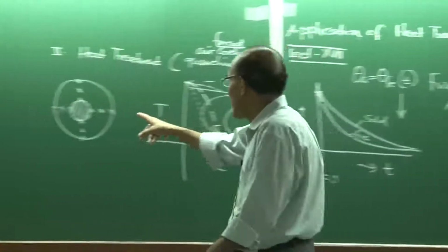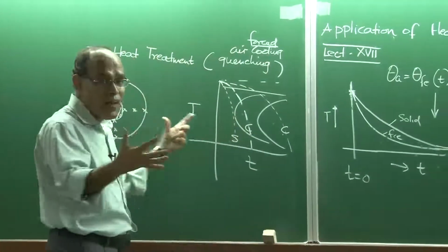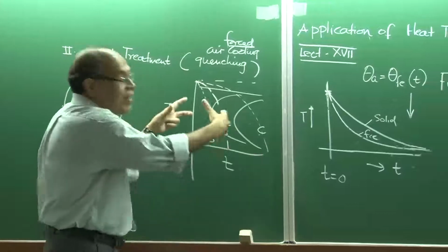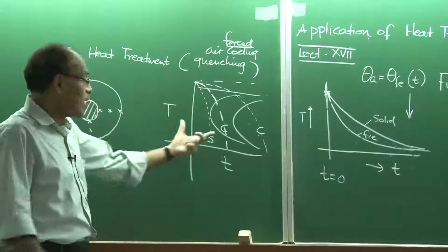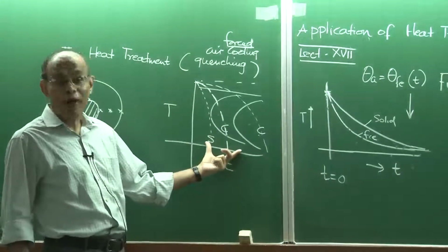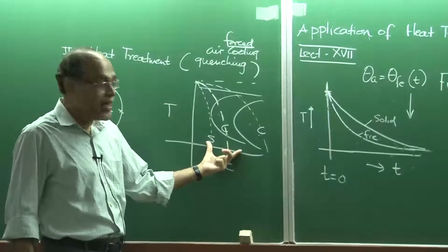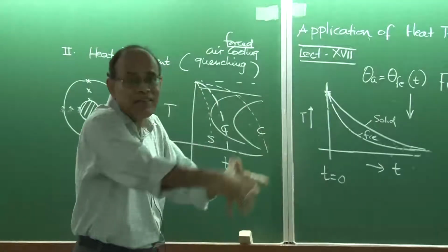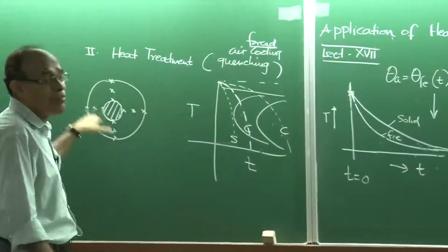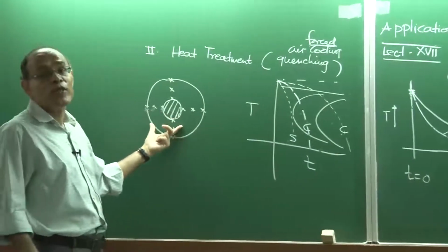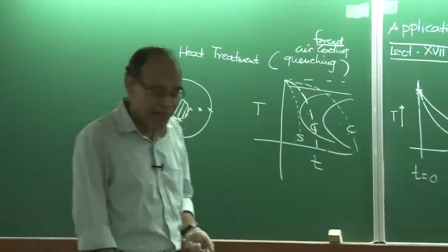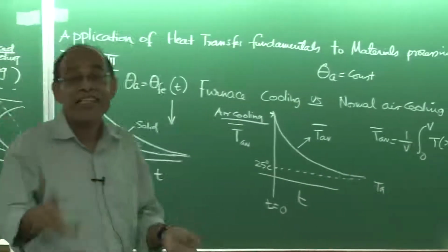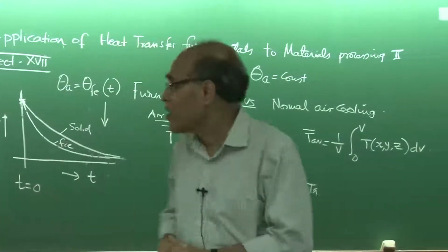In that case one will require clubbing of the heat transfer theory with the relevant kinetic information. So, if the time temperature transformation diagram is provided for that grade of steel, it can be synthesized with the heat transfer, and the combined framework can be developed to predict where within the wire we can get retained austenite, or whether retained austenite is forming at all.